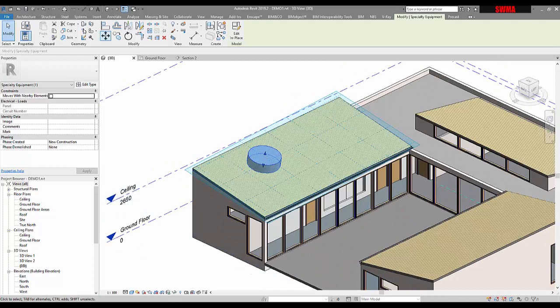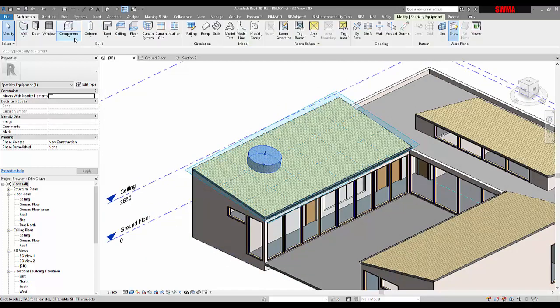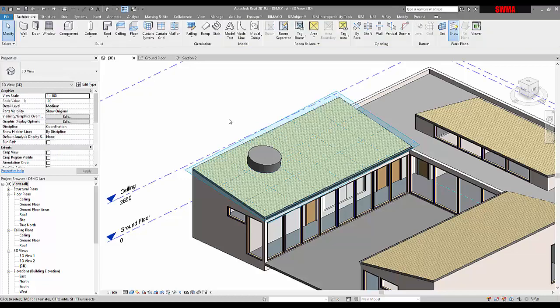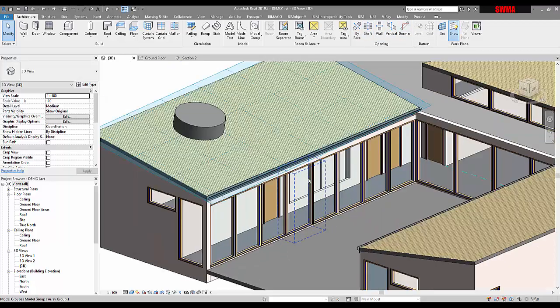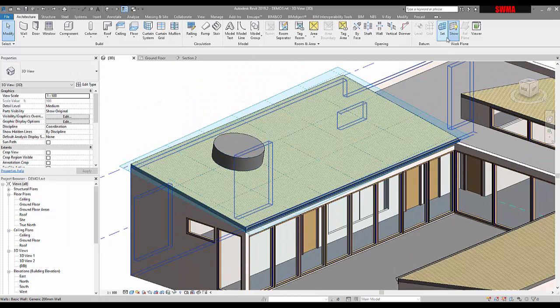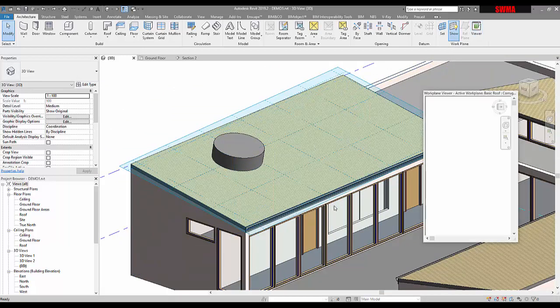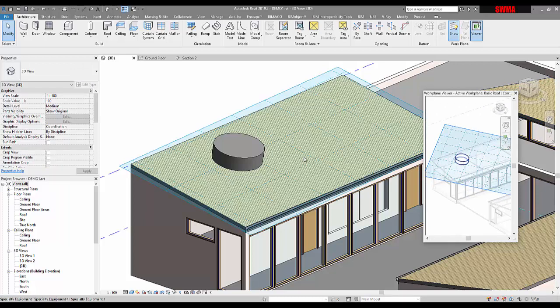Pretty simple tool, and we'll touch on other tools like components and detail, but they're pretty easy as well, very intuitive to use inside of Revit at those massing stages. So that was just a quick intro to some of the tools where you can create openings in the design down here in the hallway, and then adjusting some of the sets and the viewers to better develop your design at the early stages. Just need to go here to see everything in 3D, develop that design, and draw on the right face of the building as needed.